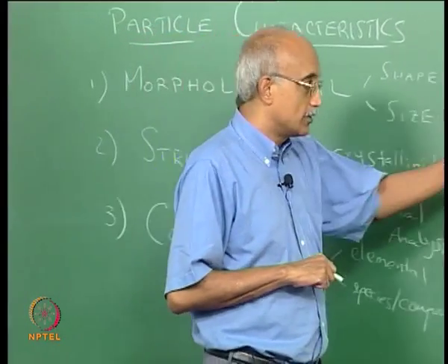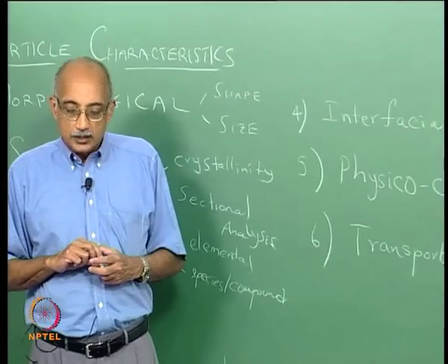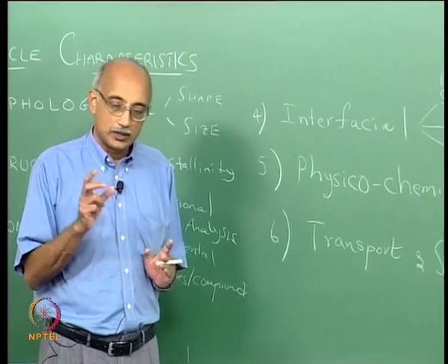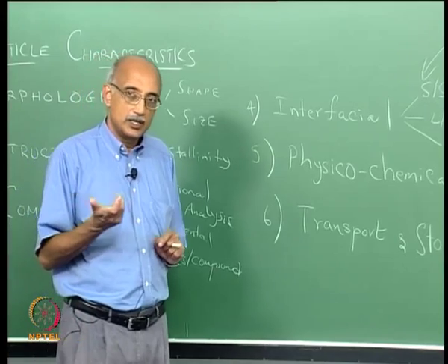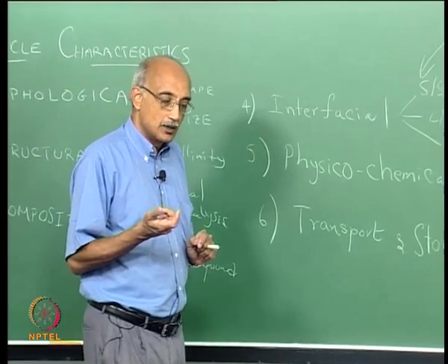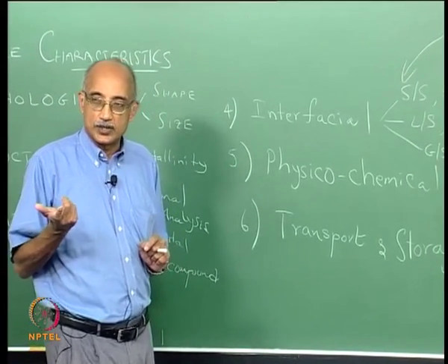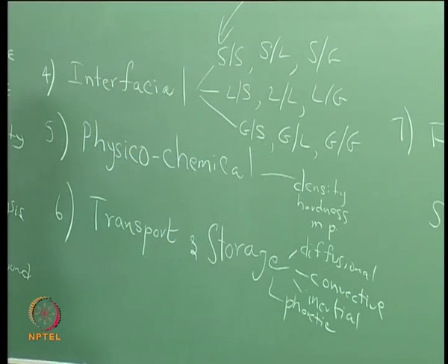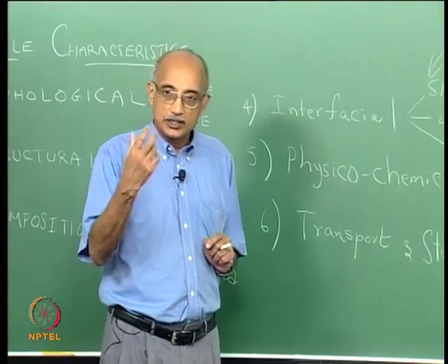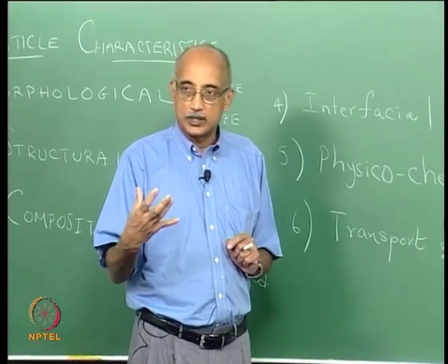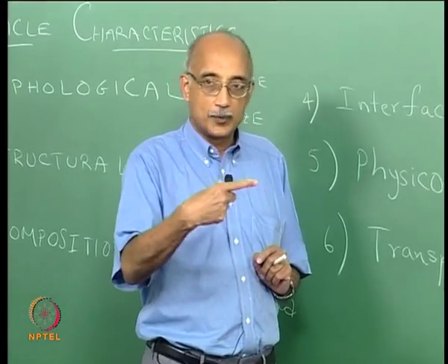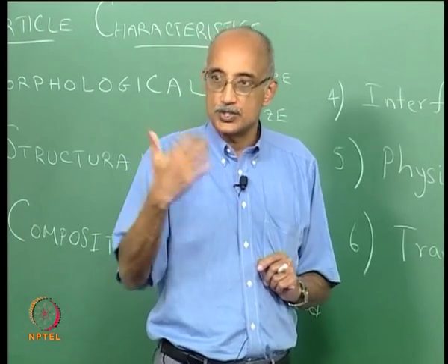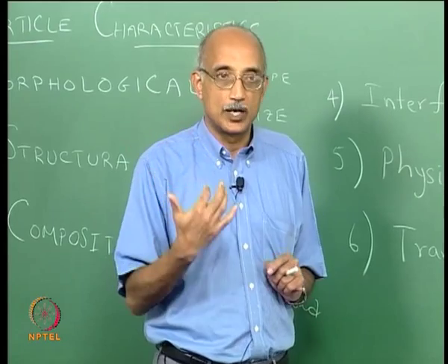When you talk about interfacial processes, the interface between the particle and its environment is not simple. It's actually a very, very complex interface, because it's not really a two-dimensional interface. Typically we tend to think of an interface as a 2D object, but the interface between a particle and its surroundings is three-dimensional in nature, because the outer surface of a particle has a depth profile also,